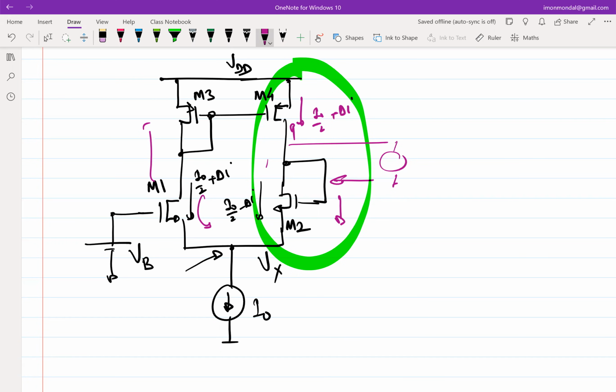So in isolation, M4 is giving you infinite impedance, but when you are making that assumption, you are inherently making the assumption that the gate of M4 is not getting excited. That's not always the case. But what you asked is a very good question. I kind of facetiously made an argument that looking into M2 is 1 over Gm, but that's not always true. What other way of looking at it is you can make the same argument without neglecting GDS.